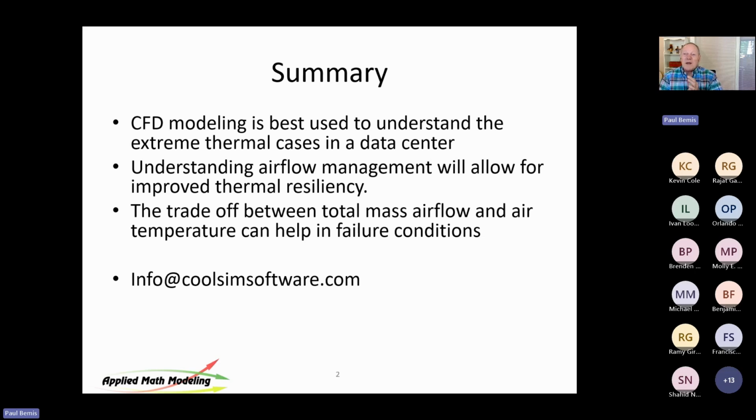With respect to grid independence, this gets a little sensitive, data centers have the opportunity to be complementary members of the grid. But that arrangement has to be struck. That arrangement has to be made. In other words, the energy consumption of a data center can go up or down with load. In fact, it goes up or down by quite a bit with load. It used to be pretty flat, but a computer today, between load and non-load state, its power consumption can vary by a factor of 5.